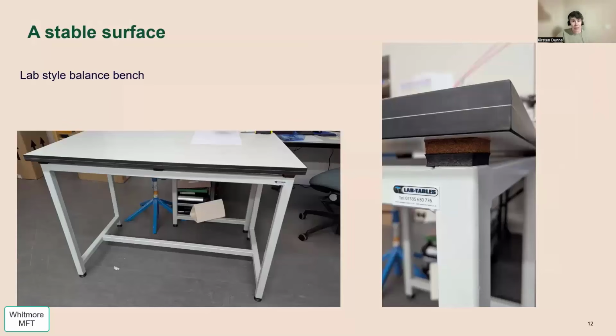So I mentioned I've got a balance bench. This is what I mean by a balance bench. If you get vibrations running through the setup when you're taking readings, it can affect your readings. It almost sort of fakes a fade, as it were. So it's important to have a stable surface to be working on. So this is our balance bench, and it's got these lovely cork pads at the corner which absorb any vibrations that do manage to come up through the floor.